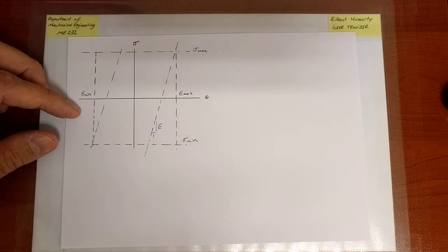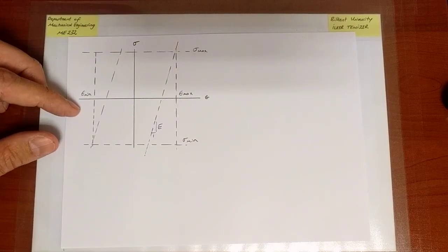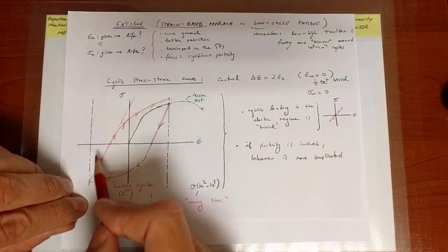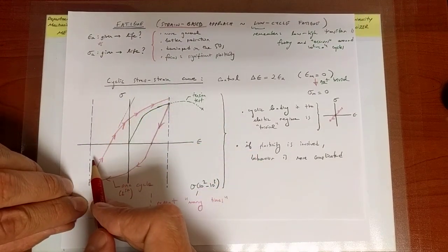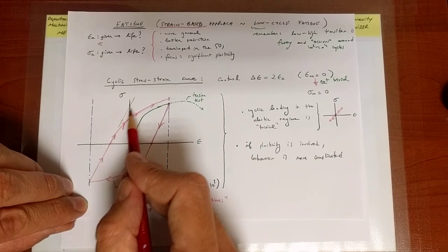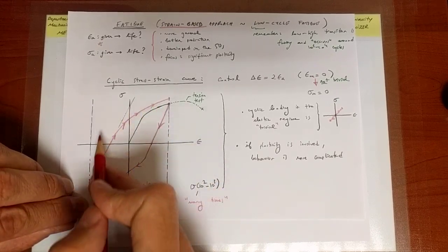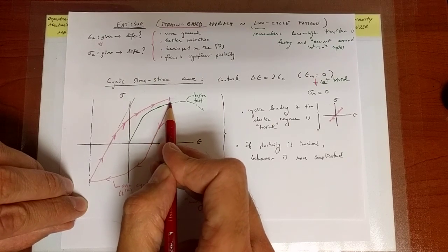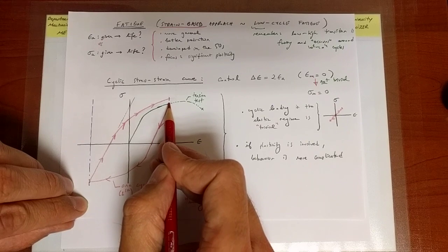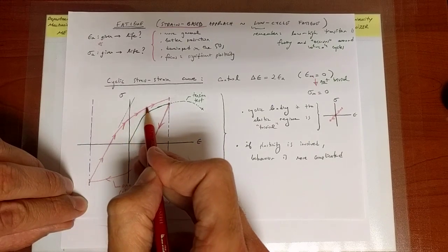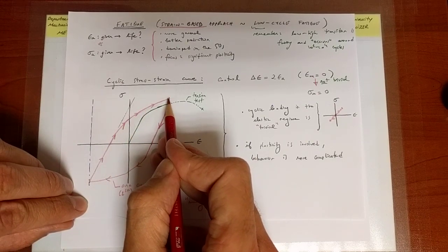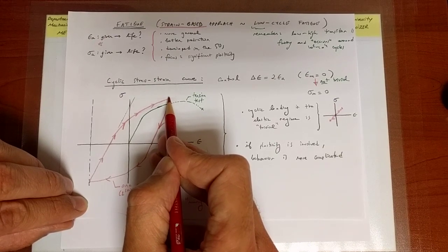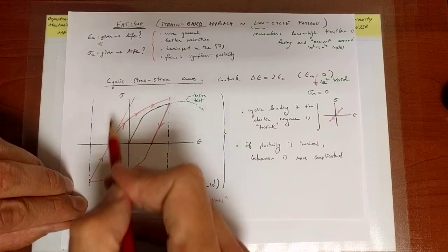Now we said that when we cycle stress versus strain many times, eventually one observes that this red line approaches a limit behavior. And in that limit behavior, the loop is closed. In other words, where I start at the maximum strain has a certain stress. When I go back, it turns out I come back to the same stress. There is no difference. If there is a difference, then it means that I haven't reached the limit or the stable loop. I need to cycle further.